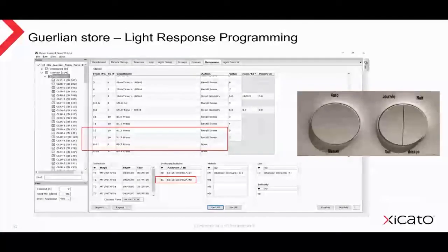So in this example, we've input triggers provided initially by time events, followed by time events supplemented by a LUX sensor during the day, then moving on to time events supplemented by motion sensors during the night. And finally, an override switch to pass control back to the shop staff at any time should they require it, such as Sundays or holidays.